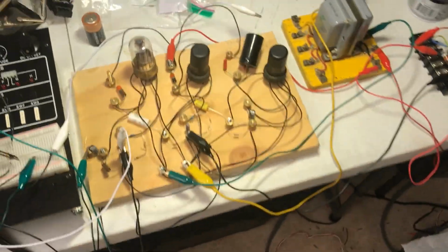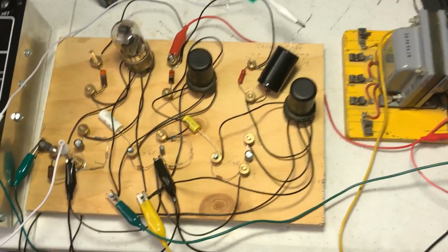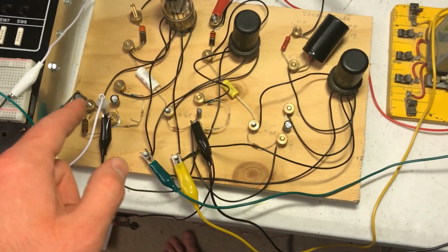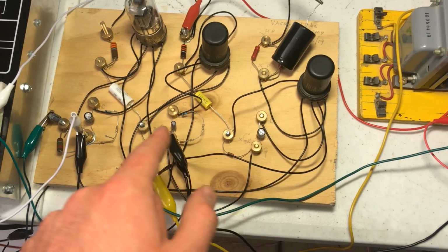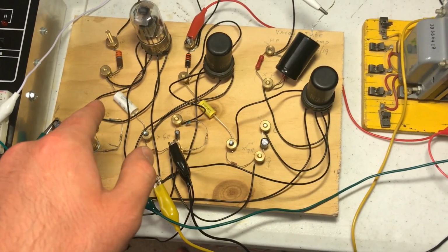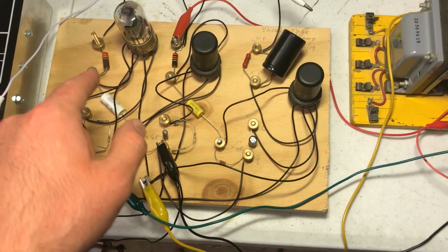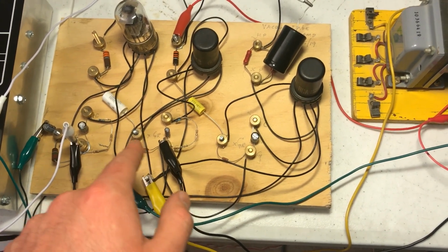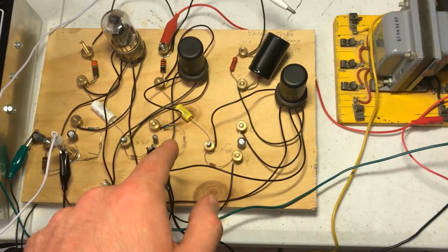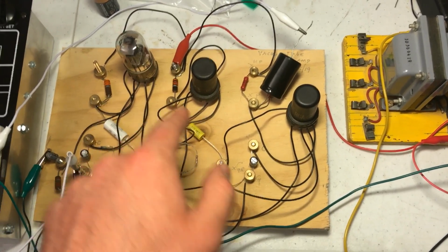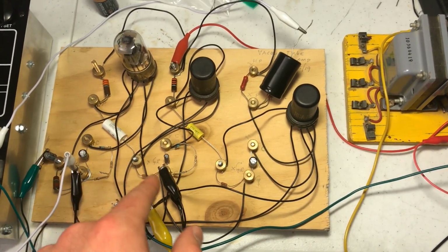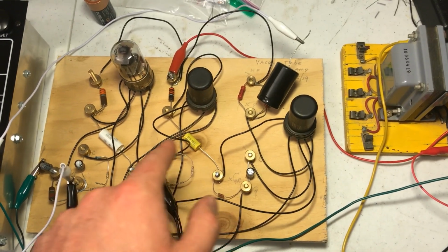But this is it. This is the vacuum tube amplifier, and as you can see, it gets capacitively coupled in. That's the grid. Ground is the bottom one. The filaments, these two. Cathodes, the next one. You can see it goes from plate, capacitor, next grid. That's your grid leak right there. 770 ohm or 35 kilo ohm. We're close. Cap out, cap in. Self-bias resistor network is here.